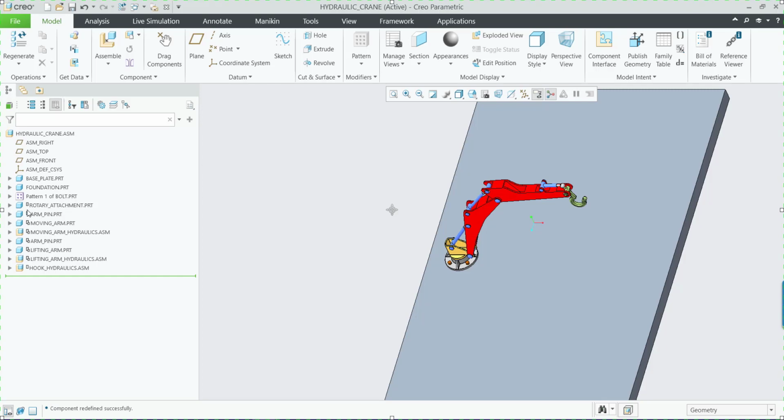mechanism connection. So now for the rotary attachment, you can see this icon over here, a rectangle inside which there is a dot. That's nothing but the packaged component. Packaged component means it is having a mechanism connection. It is not fully constrained. It is allowed at least 1 degree of freedom as free. That is the indication by this icon over here.